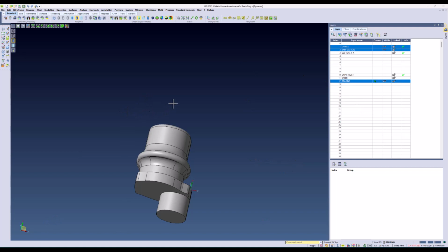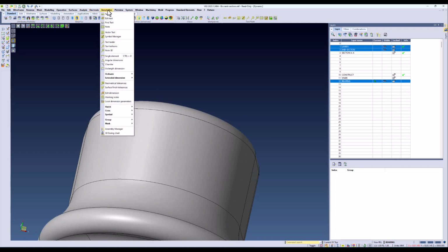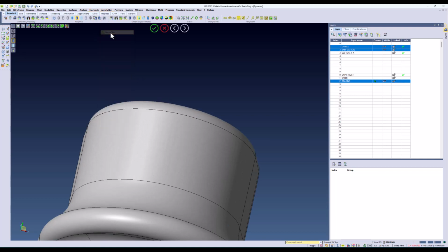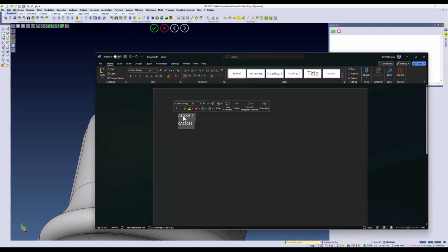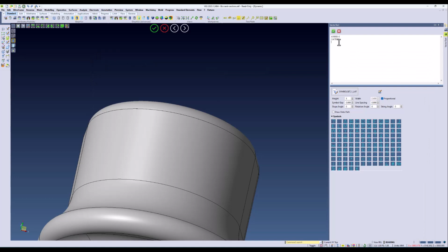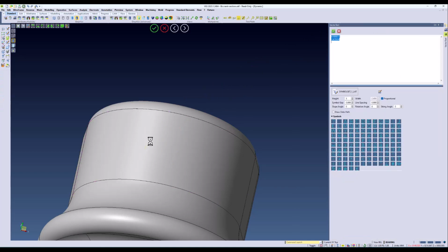It's never been easier to create engraving and model text into a design. So in this example, we're going to use the vector text command. Within vector text, we can copy a part number right onto the model and paste it into vector text. What this command will do is automatically create the text as profiles and curves, and it also creates this text as single line, making it easier for you to do some design work.